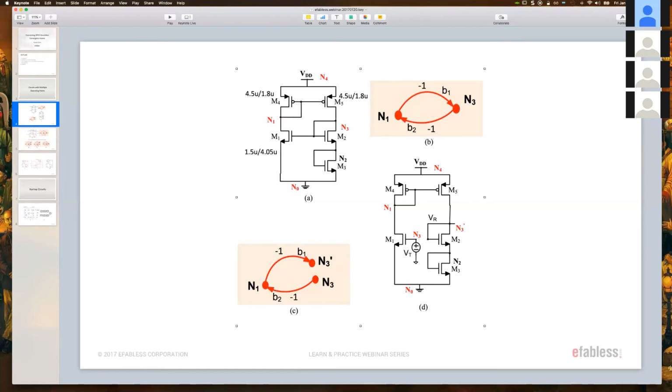And the approach to actually understand the operating point, one that works the most, is to understand where the circuit can go if you do some sort of artificial sweep. So in this case, breaking the feedback loop here and applying a signal directly to that artificial input and seeing what the return is. And obviously, a valid point is where you have a solution where they intersect.